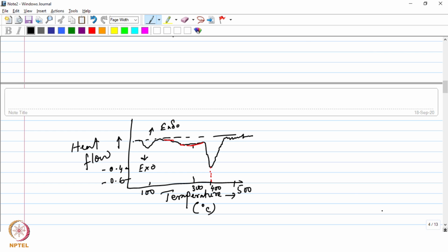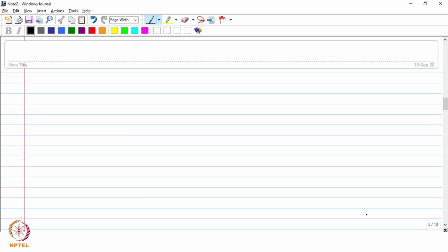So now we need to understand what exactly happens during the recrystallization process. Okay. So the driving force we have understood: it is the stored strain energy which is given to the material by the cold working process. And now as you heat it, this is going to be released, and we have just discussed how that occurs and how you can visualize that experimentally.